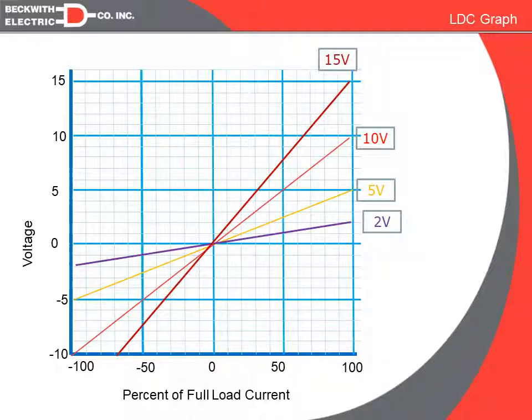So if we want the regulator to always be raising the voltage at the point where it's at, we would want a positive value in the forward direction and a negative value in the reverse direction. Now, if reverse power is due to sectionalizing and we have regulate in reverse selected or regulate in reverse measured, then we don't have to flip the sign because it knows the source has changed.